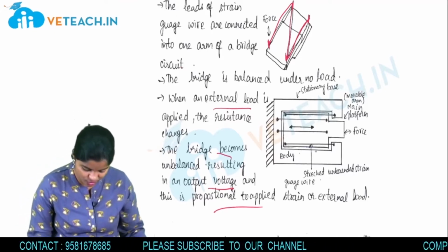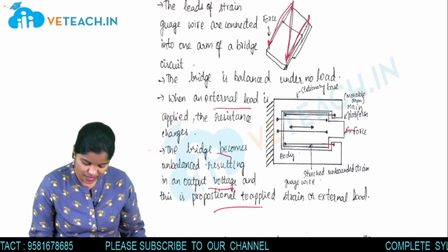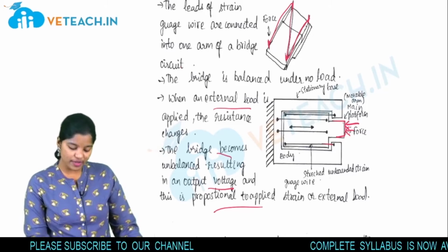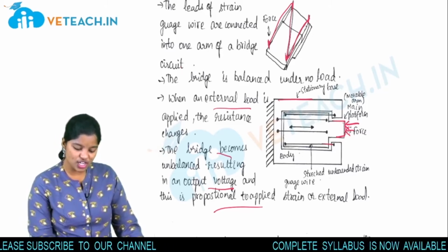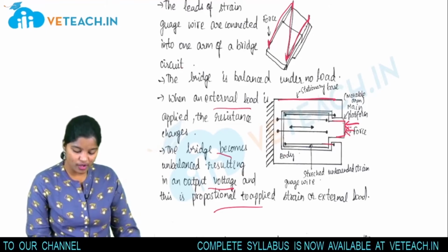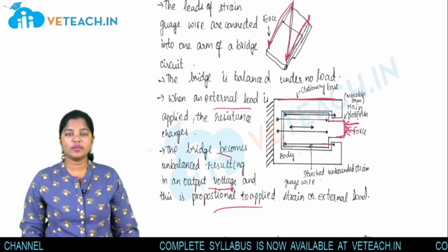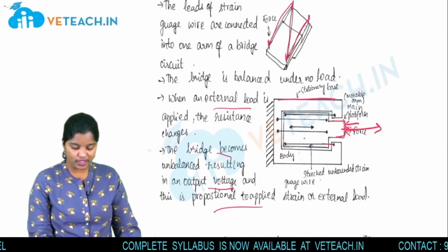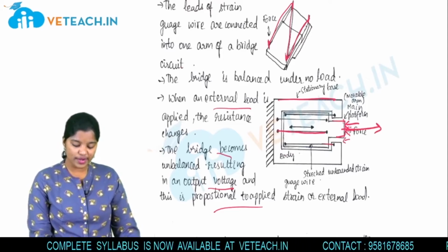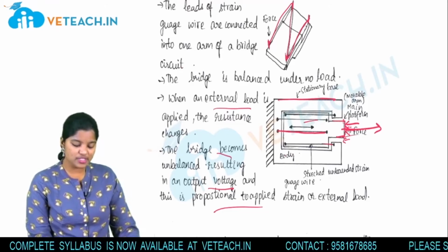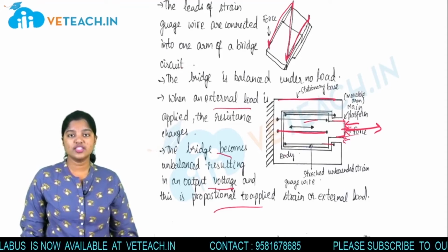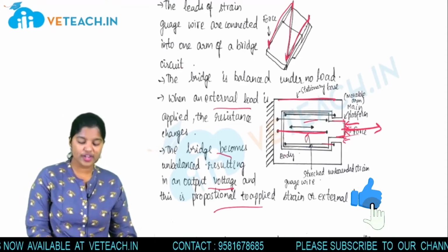So here, the stretched bonded strain gauge, this is the force which we are applying. This is the movable platform, that is, we can push it inside or we can take it outside. This is nothing but the body. This is the stationary base, which is not moving, and this is a movable arm. This main platform is nothing but a movable arm. Whenever we are pulling it outside, tensile stress is caused and a change in resistance occurs. When it is moved inside by applying some force, it compresses, and correspondingly a change in output voltage is obtained since the resistance of the strain gauge changes.